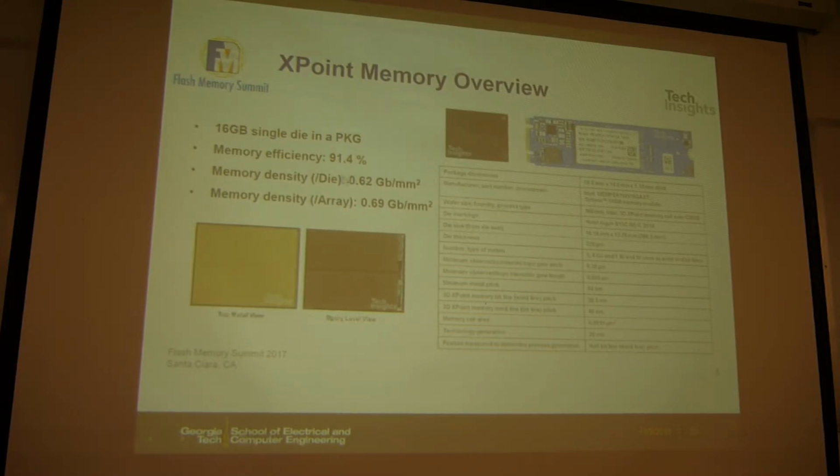And the capacity of this chip, I think the first generation, that's 16 gigabyte. And if you look at the chip area, it's like this 60 millimeter by 12 millimeter. So in total, it's around like 200 millimeter square. And you have this 16 gigabyte capacity. So you can convert that to the density. Let's say the gigabit per millimeter square. So you get this number.